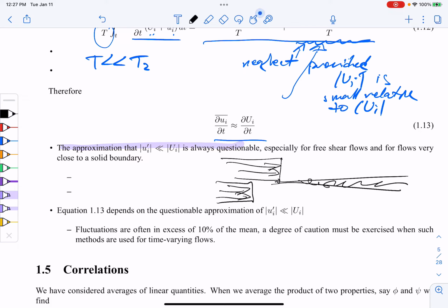And this also means that our time averages for analysis, especially for time marching numerical methods for solving steady flow problems, might encounter some major problems, because the unsteady terms we're calculating in unsteady RANS are nothing like fluctuations at all. We're just really getting the average quantities. The average quantities are changing. The statistical quantities, the fluctuating quantity, we never really know from a RANS solution. You'd have to do a totally different technique. So you're really only getting in an unsteady RANS solution the variation of the average values, which I just erased. Just write U bar. How's that?